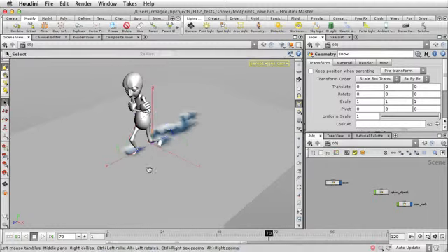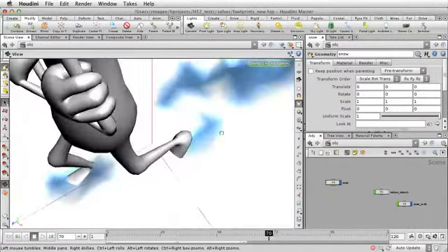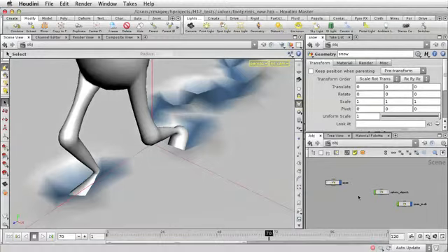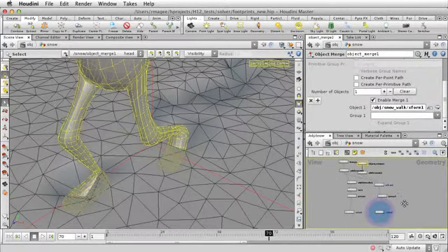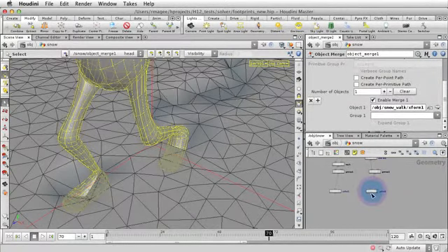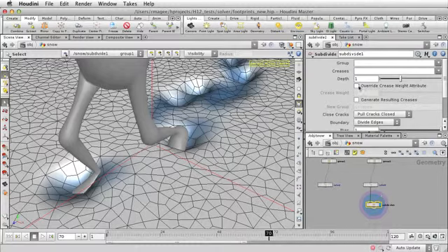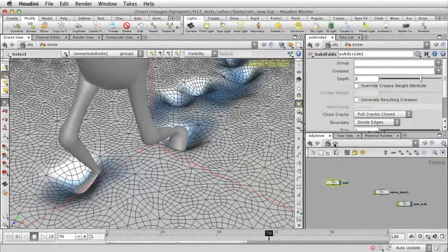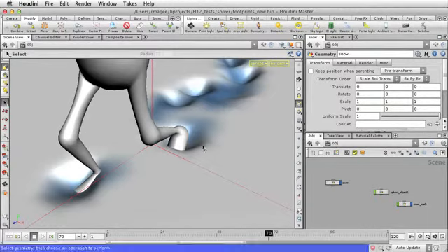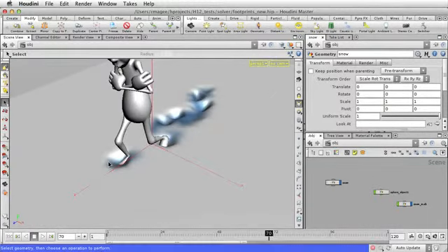Now let's just get the select tool, zoom in, and we can sort of see that in the surface there. Now, oops, certainly didn't want to do that. If we go down to the snow, if we want to, like I said, we could add a subdivide and maybe add a depth of 2. And you see how we get a nice sort of look there. This will be a lot slower, but it has a nice snowy look to it, which you could work with.